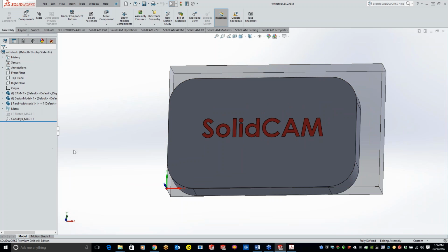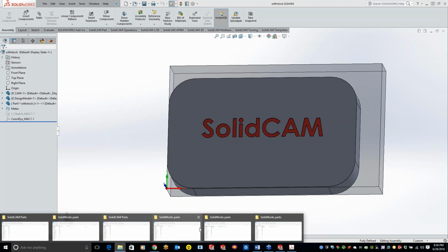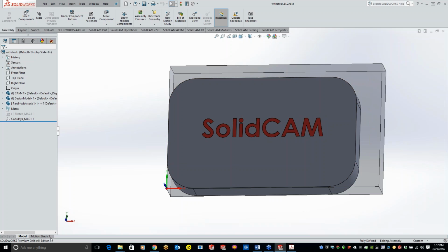But if you are getting errors, Michael, when you're doing that save as, more than likely there's something stuck in your temporary folder. If you clear that out and then do your save as, you shouldn't have any issues at all. It could also be because with your Windows 10, UAC might have been up and was causing the issue. Like I said, communication between each one is extremely important.